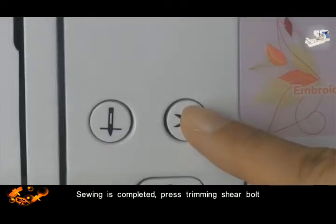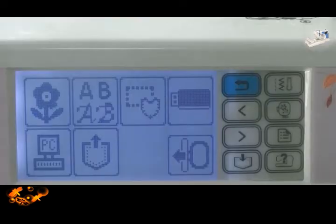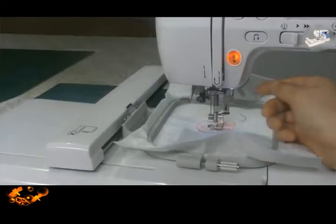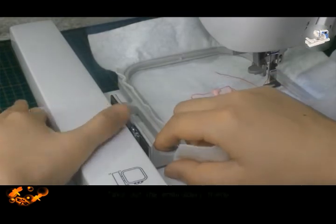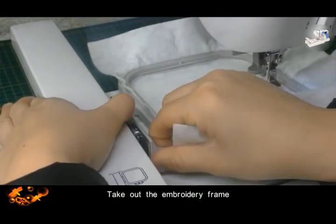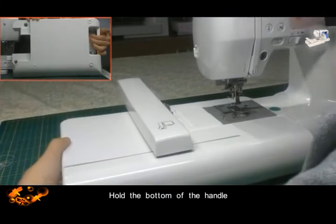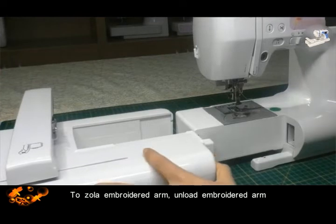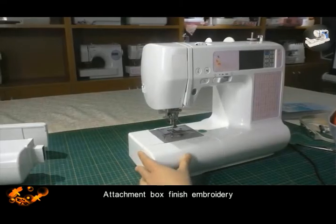When sewing is completed, press the trimming shear button. After the dotted box is out, lift the presser foot. Make the embroidery arm come out automatically. Take out the embroidery frame. Hold the bottom of the handle and unload the embroidery arm. Put away the accessory box to finish the embroidery.